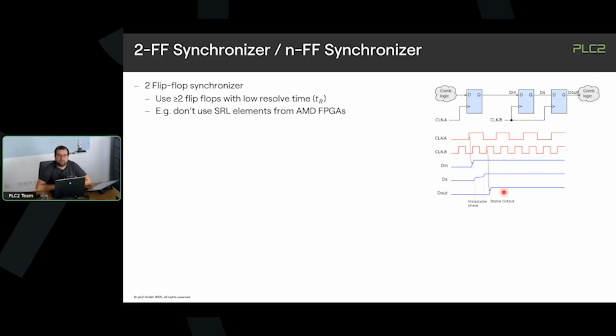From this diagram, we can also guess what's happening when you increase your clock frequency. It might be that this flip-flop sometimes takes longer to resolve. So the higher your frequency is and the smaller your technology gets, the more flip-flops you need. I had an unofficial discussion with AMD and Microsemi people, and they recommend nowadays 3 flip-flops for current technology.